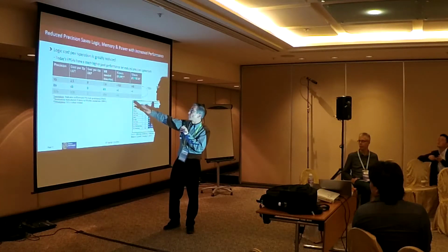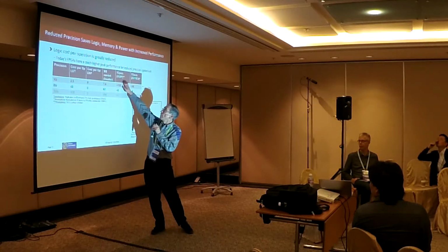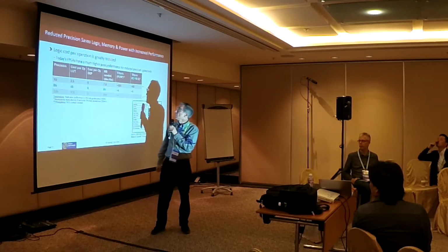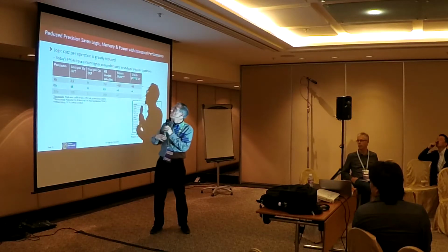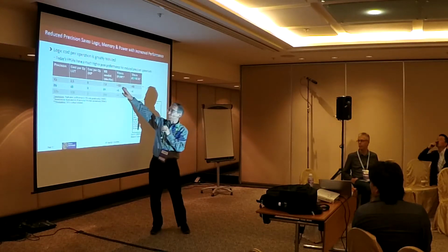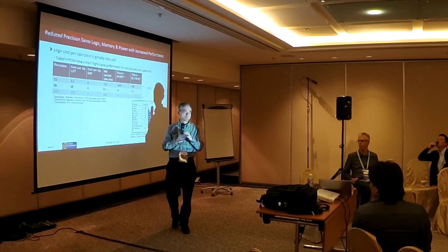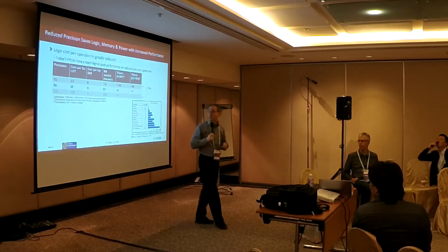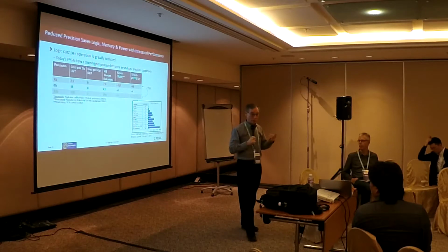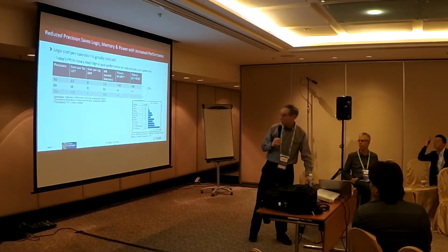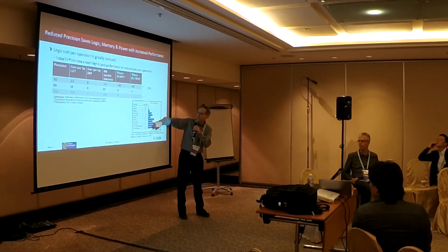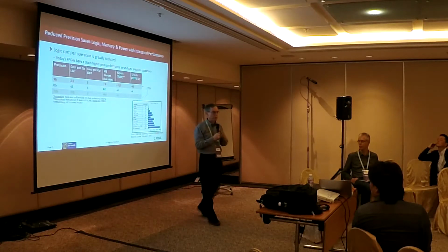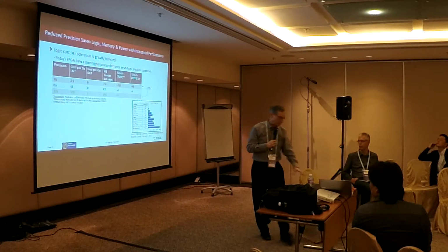What's our performance? Here you can see this is what's called a Virtex UltraScale+ device. We can do 100 teraops if we're doing 1-bit functions versus a single teraop if we're doing 32-bit functions. So you see there's a dramatic performance improvement, 100-fold, by going down in the number of bits. And you can also see over here the relative energy cost in one of our devices for these types of functions.